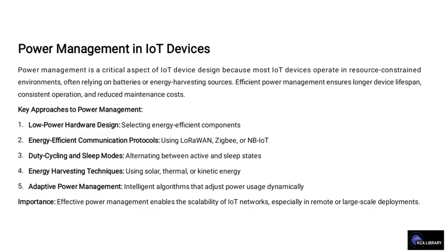In doing this, we have five different approaches for power management. The first one is low power hardware design, that is selecting energy efficient components. Another approach is the energy efficient communication protocol. Also have the duty cycling and sleep modes, and this deals with alternating between active and sleep states.